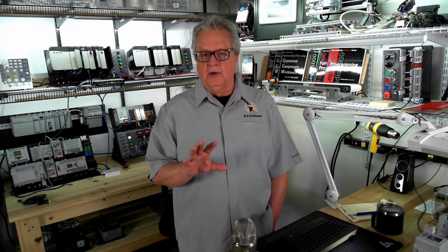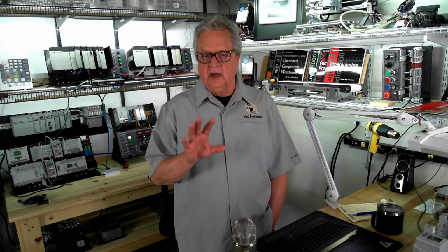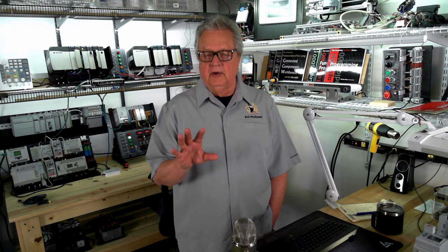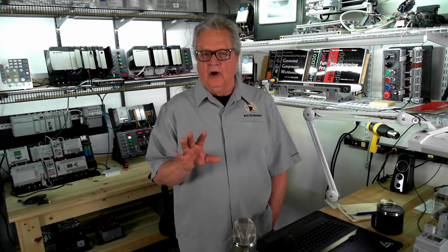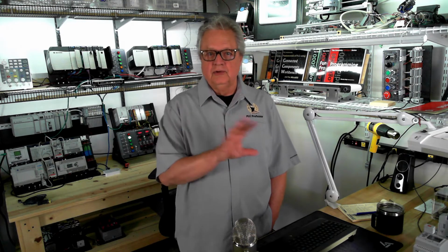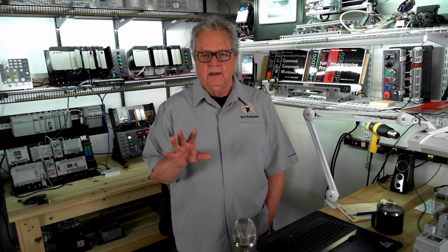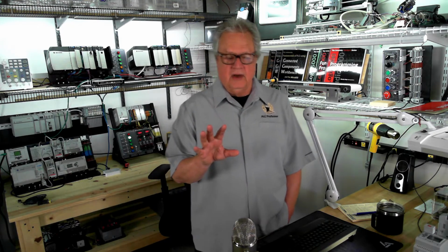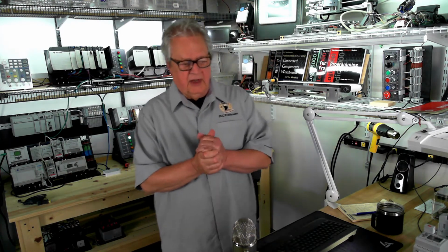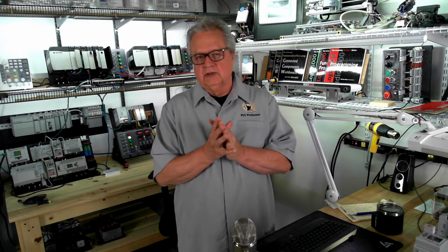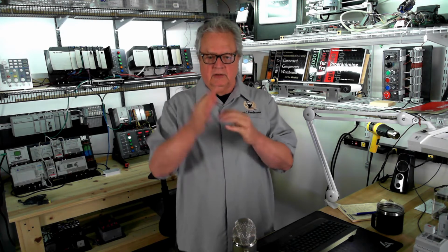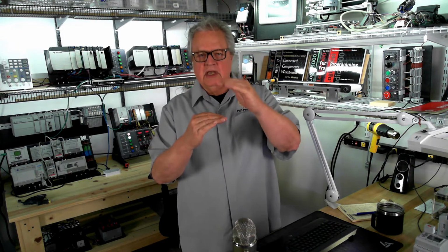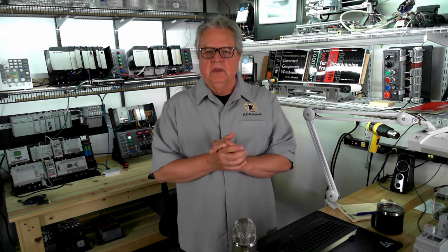Now at this point, we've really not done anything with I/O, inputs or outputs. Remember, those are global variables, and those bits of memory are more or less directly connected to screw terminals in a sense. But we're still not there yet. We're not doing I/O yet. What we're going to do in this lab project is explore the relationship of multiple rungs of logic. In other words, is there any relationship to the order they're scanned in, etc.